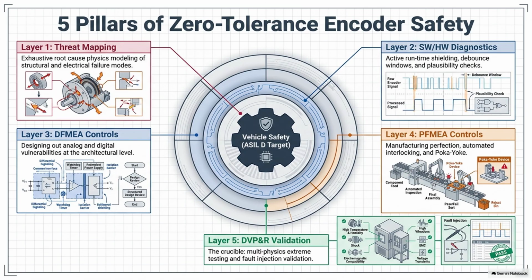But looking at the notes on electromagnetic interference, EMI, that seems to be the much larger threat to magnetic encoders. Oh, definitely. Because inside a modern dual-motor powertrain, you have this very compact, space-constrained housing with high-voltage silicon carbide, or SiC, MOSFETs. And those transistors are chosen specifically because their wide bandgap allows them to switch massive amounts of power on and off at incredibly high frequencies. Right, which vastly improves the motor's efficiency. It does, but that rapid switching is actually the core of the problem. We are talking about voltage changes, a dV/dt rate of greater than 10 kilovolts per microsecond.